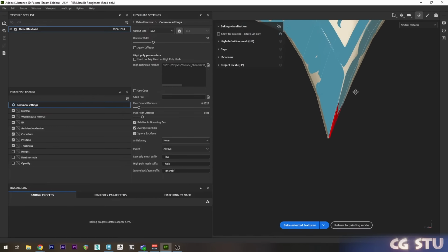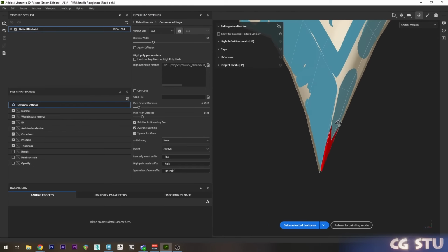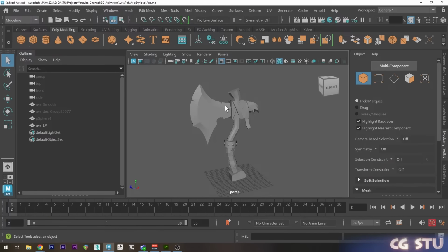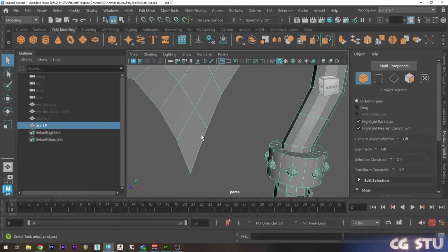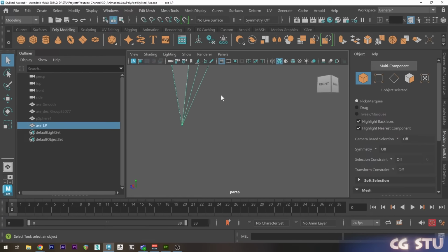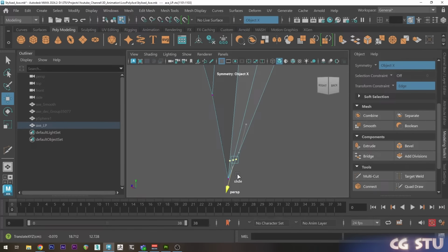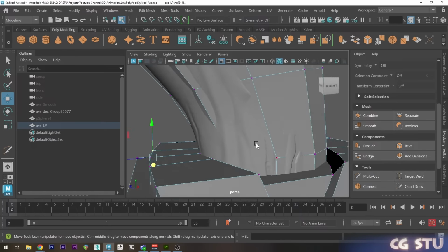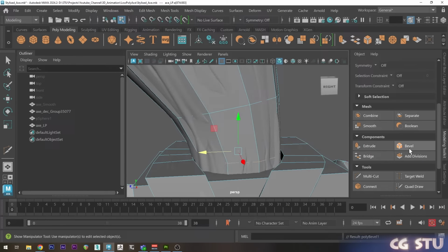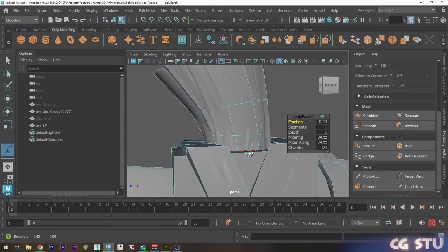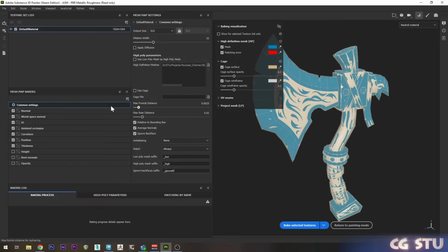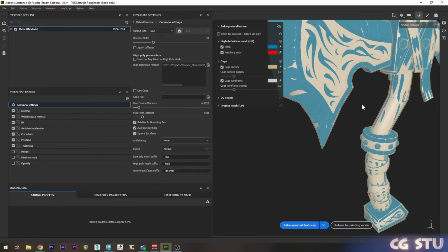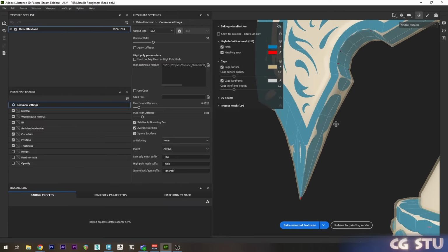And I can see here I've still got a few little areas that I can fix up. So I'll go back into Maya, and I'm going to add a little bit more detail in these areas, and hopefully that will fix the projection cage for us. And move parts around until it matches the high poly mesh a little bit better. So now when I bring it back into Substance Painter, I can get the cage a lot smaller. Now you can see the cage matches a lot better.